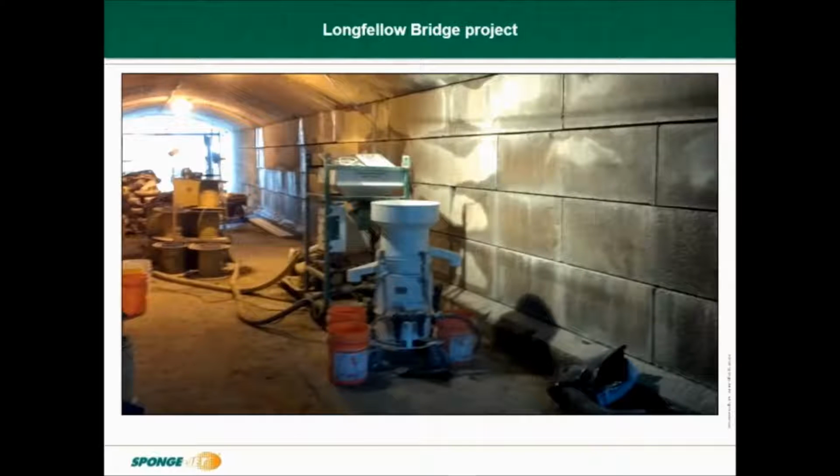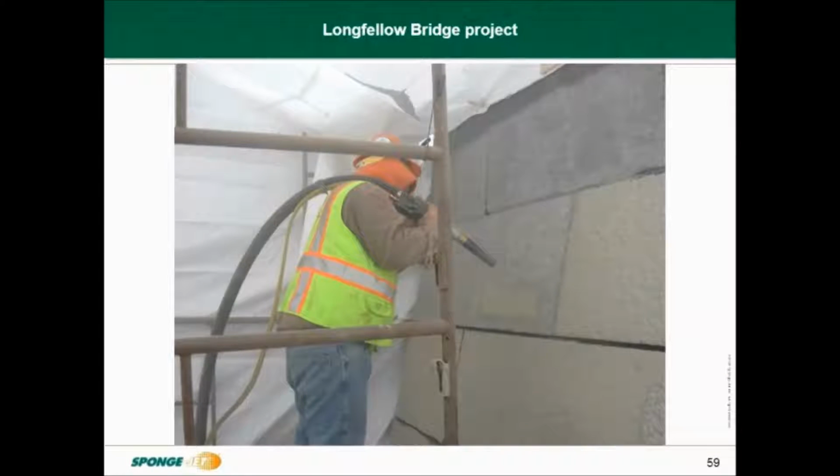The setup of the equipment was inside the tunnel of the bridge structure. We kept it out of the weather and didn't expose it to rain. United Stone was able to achieve the desired cleanliness and finish on the granite while maintaining production speeds of up to 27 square metres per hour, or about 5 square feet per minute. Sustaining the cleaning rate was pretty critical to return the massive blocks for reinstallation, which they achieved with one blaster and one system, on one hopper and one recycler.